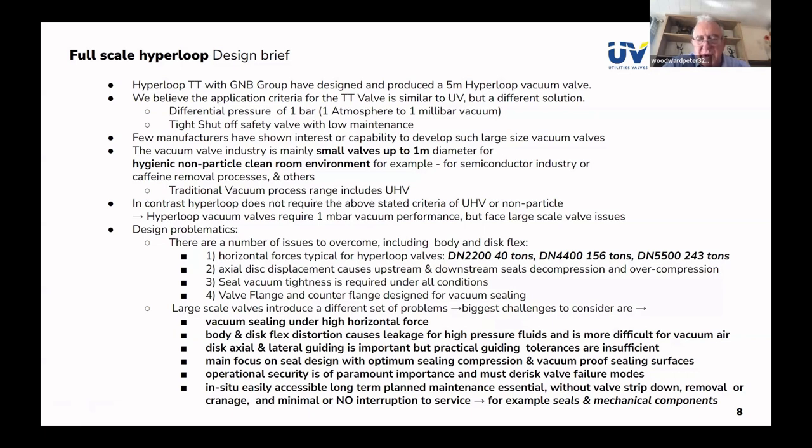But what we really want here is to control the overcompression of the downstream seat and also control the degree of upstream seal decompression. So we've looked very closely at how to achieve that with a different approach to guiding, which has been successful.